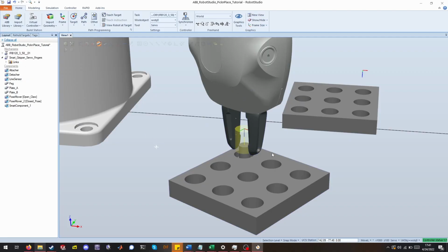Furthermore, regarding how line sensors work, they sense objects through intersection, which is to say they notice some part is physically jutting into their volume and crossing over. The reason why I bring this up is because sometimes it's possible to render parts as being hollow to help save on computing power. It's basically just more efficient. That might cause issues with sensors not being able to detect them if they're, say, fully enclosed within a part. Say if this was considerably thinner and all the way in the part, it might not register it. So just keep in mind and make sure that either the radius is wide enough or there's some amount of protrusion from the part you're trying to pick up to properly sense it.